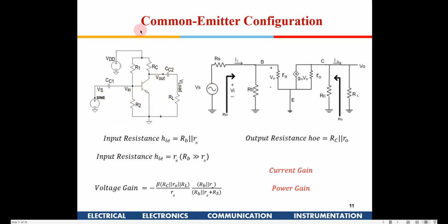So now you can consider this whole amplifier as a load, which is represented by the input impedance. So in those cases, like if you have an antenna of 50 ohms, this will offer very high input impedance. So whatever energy is being captured by the antenna doesn't get transferred to the amplifier. So in such cases this amplifier is not suited. So we need to look for an amplifier which has got low input impedance, because most of the antennas have very low input impedance. Okay, they are of the order of 50 ohms.